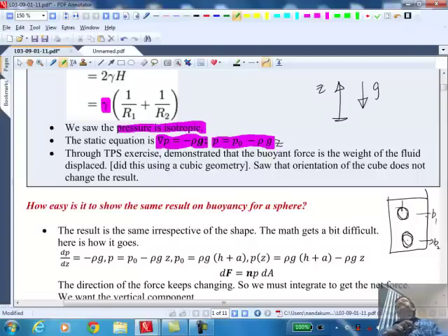Why is that? If I design a submersible boat and I take it deeper and deeper into the ocean, at any point I can add water or release water to make its effective density the same as the surrounding one. So I can make it neutrally buoyant. If you look at submarine designs, these are the issues that you need to worry about. So I want to go from one level to another level. How do I do that? And then at that level I want to just stay for a while. What do I do?